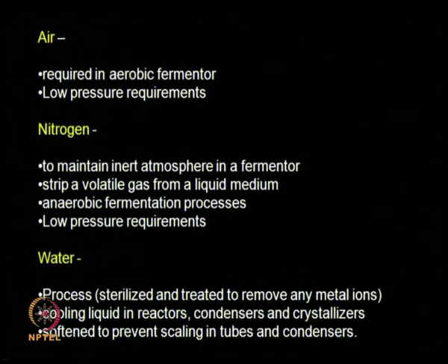Air. So where do you use air? Air is required in aerobic fermenters. So we need to have a facility for preparing, getting air, compressing air, purifying air, sterilizing air, because in an aerobic fermenter we cannot just introduce air directly from the atmosphere.